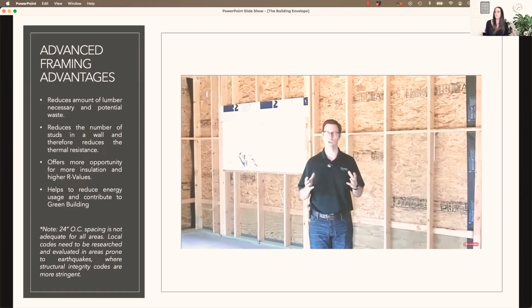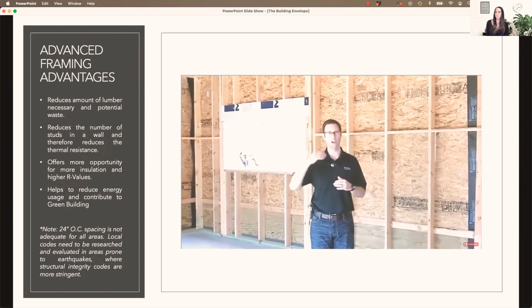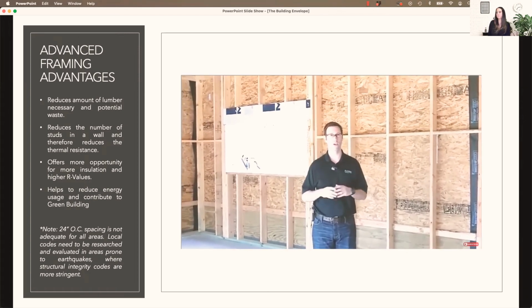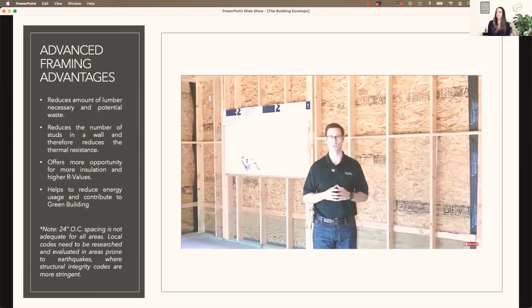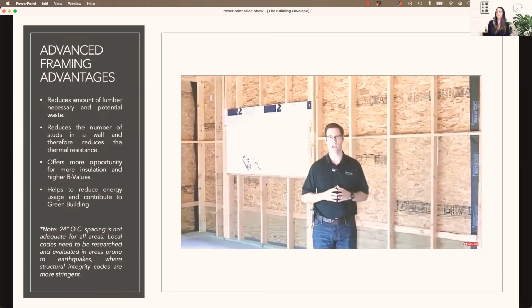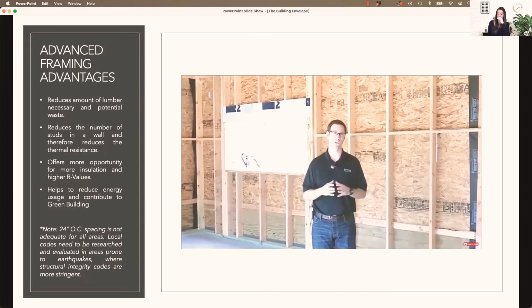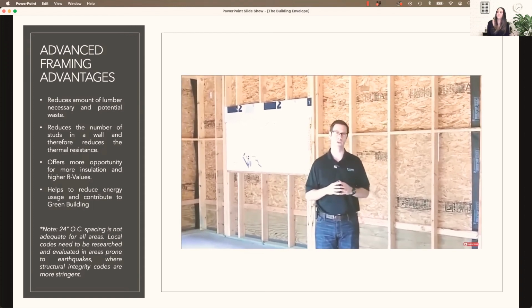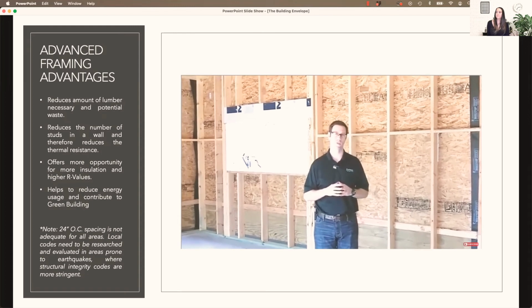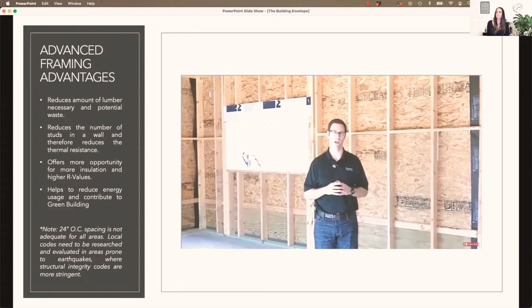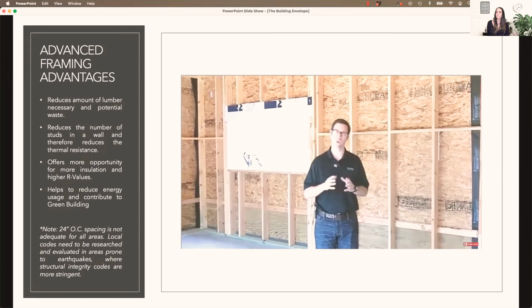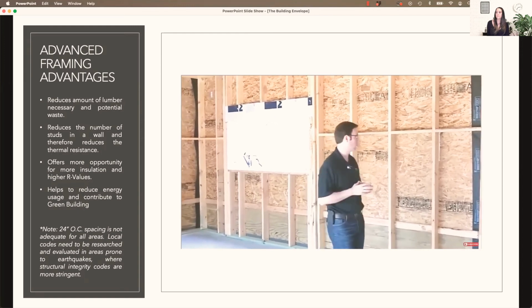In this house, we took an approach that is not quite all the way, but I think really makes sense for most people that are building a new house. I'm here in Austin, Texas. This is a cooling dominated climate. We do need some insulation in our walls, although not nearly as much as some other climates like the Northeast or in really cold climates. But I do prefer to frame all my houses with 2x6 exterior walls.